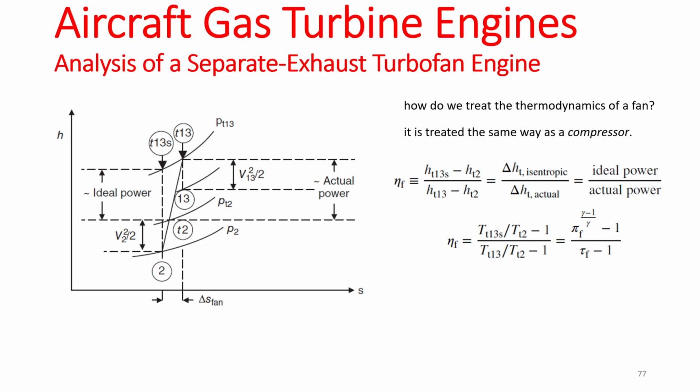So what you can do to simplify this is to use the definition of the enthalpy, which was CpdT or CpT. And the Cps are not going to change in the fan, since there is no burning, no fuel added, nothing, so we can safely assume that the Cp at the exhaust and the inlet are pretty similar to each other.